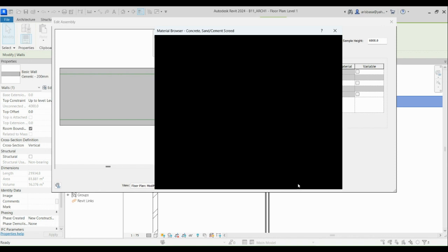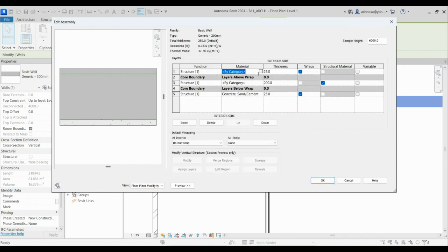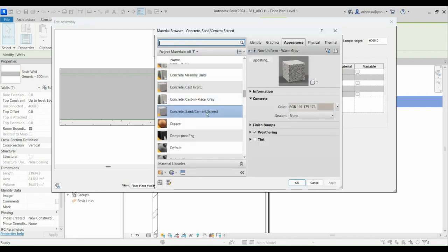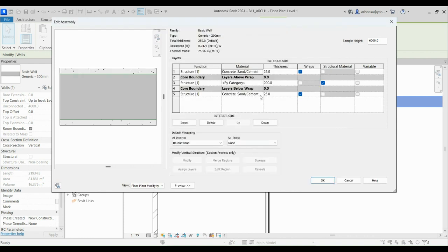Now click OK, and then also here, and cement. Okay, right. And this should not be a structure. These are finishes. The structure is the middle, right? This is a finishes. So you click finish number 2 because it's inside. So finish number 1 will be outside. So now we have just created, customized a type of wall. Then we click OK.